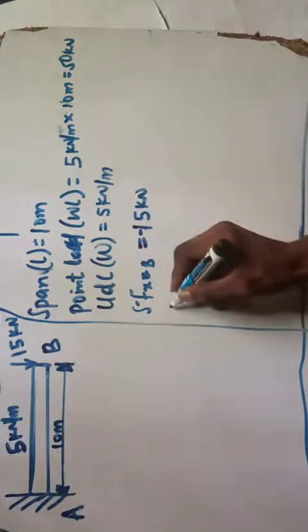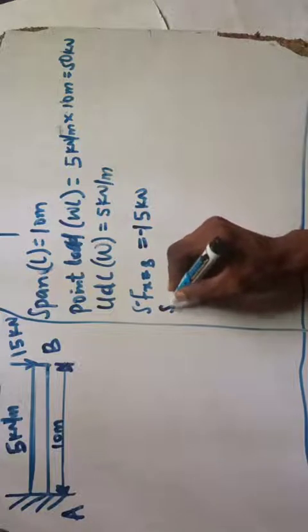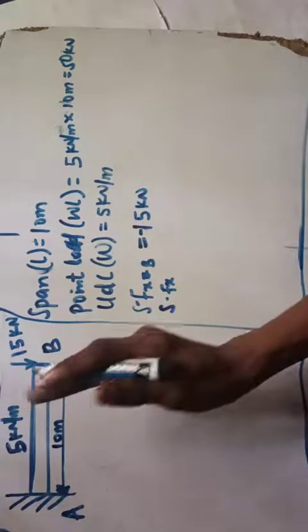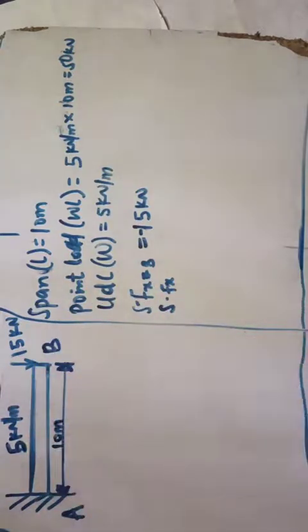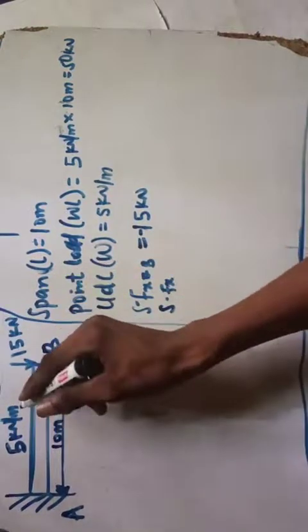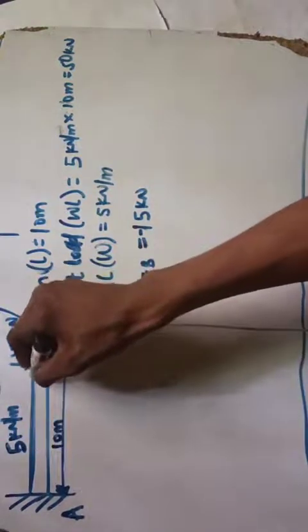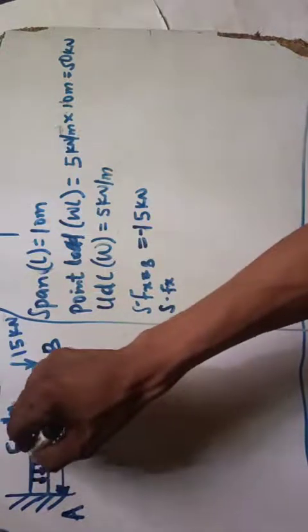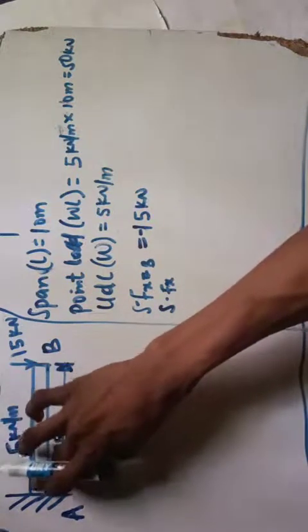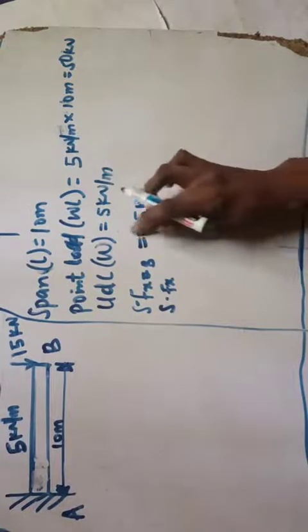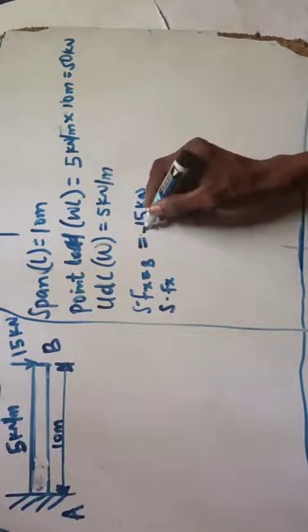So next thing also is the shear force at X. Now, for UDL, you must section it. This is a force acting on its own as a point load. Sometimes you might be very lucky to be given it like this, but not most times. Sometimes you can just be given the parameters. It's UDL. Okay. Now, it's very important you section your UDL, since it's UDL.